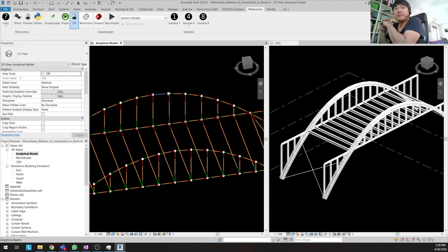Sorry, there was a question in relation to this about calculating curved bridge beams. You've explained how you can convert this into a single curve in Revit. But when we are working with the geometry in Karamba and calculating it as a structural analytical model, we have to split every curved element into separate line segments in Karamba before you can calculate it.